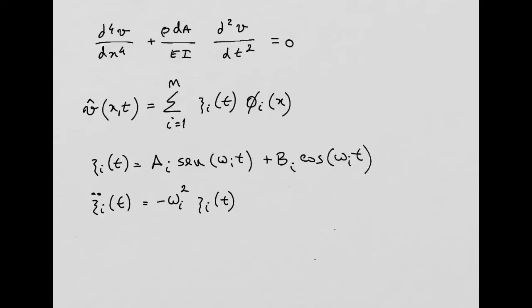The difference here from what we did last week is that we are going to have not only one function phi, as a function of time, but n functions phi as a function of time, right? So the more functions phi we have, or the higher this n is, the more accurate our solution will be. Don't forget, this is an approximation method. Something you do in FEA, right? This is equivalent in FEA to refining the mesh, getting more nodes, getting more n terms in this summation, right?